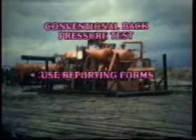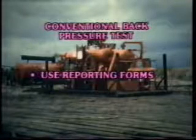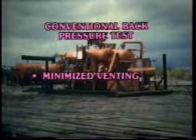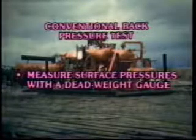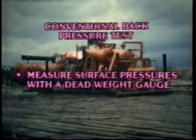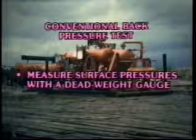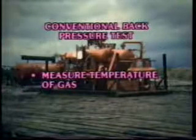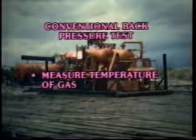The observed data and calculations are to be reported on the prescribed forms. Vented gas volumes shall be minimized. Record surface pressures with a deadweight gauge. Subsurface pressures with a properly calibrated bomb. Flowing surface temperature should be reported. The IOCC recommended conventional test procedures are as follows.